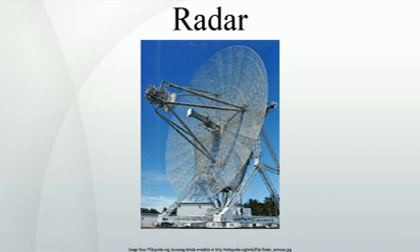Frequency modulation. Another form of distance measuring radar is based on frequency modulation. Frequency comparison between two signals is considerably more accurate, even with older electronics, than timing the signal. By measuring the frequency of the returned signal and comparing that with the original, the difference can be easily measured. This technique can be used in continuous wave radar and is often found in aircraft radar altimeters. In these systems, a carrier radar signal is frequency modulated in a predictable way, typically varying up and down with a sine wave or sawtooth pattern at audio frequencies.